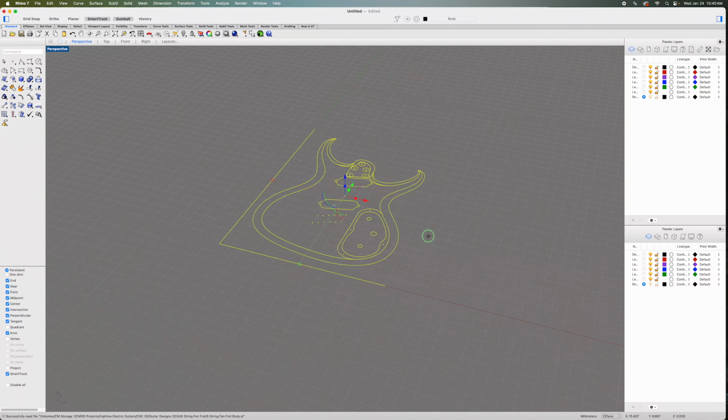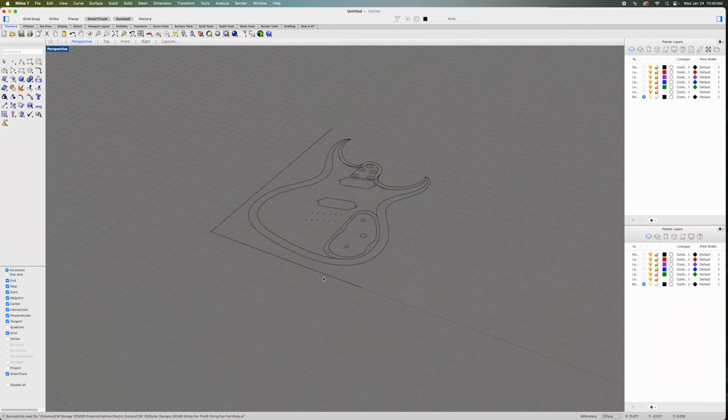As you can see, it's lying flat on the surface. Now this L-shaped line here is part of the bounding box, and it's only showing the bottom and leftmost edges of that bounding box. It doesn't show the right or the top. This is a glitch in Rhino. I think it started with Rhino 7. I didn't notice it in Rhino 5 or 6, which would always import the entire box. But for some reason in Rhino 7, it's leaving out the right side and the top. So I hope they fix that for Rhino 7, and perhaps they fixed it for Rhino 8. I don't know, I haven't upgraded yet.